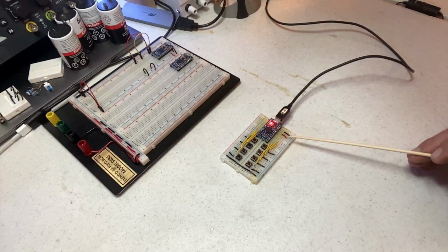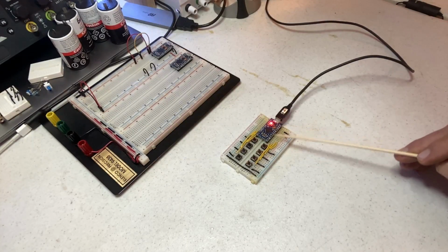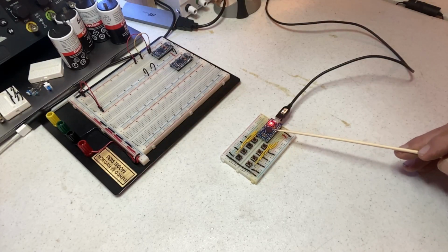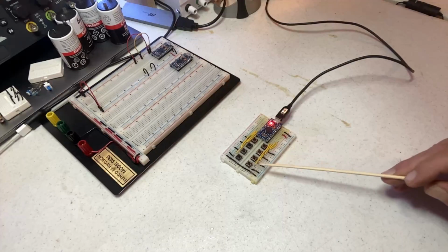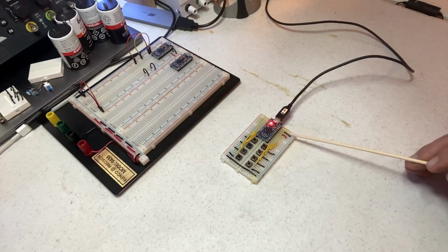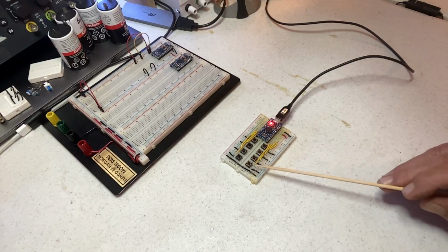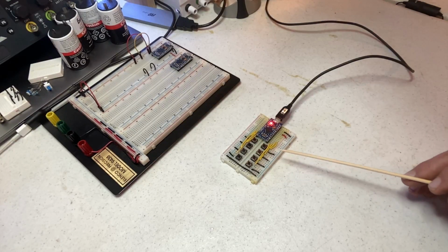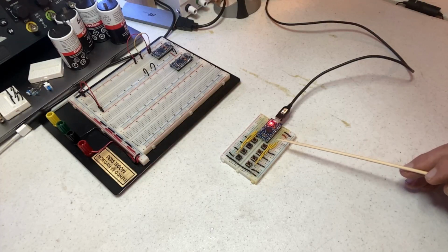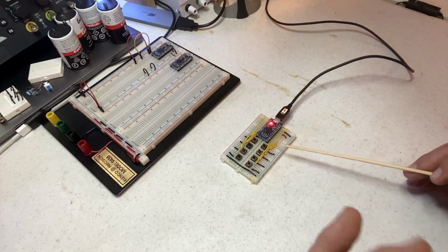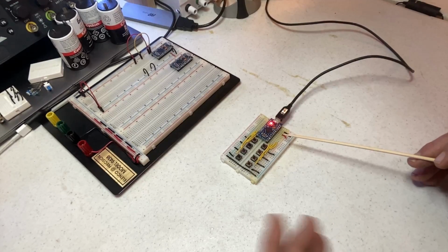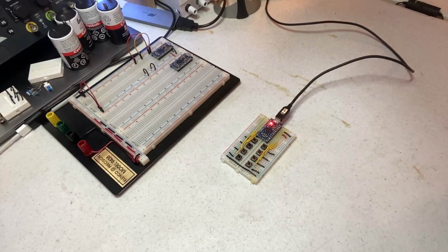Technically I don't need this red power jumper because I'm not using any power. What I'm doing is using the internal pull-up resistors on the pins inside the Arduino, which you'll be able to see in the code. And then I'm just taking the ground through each button and bringing it back into a pin on the Arduino to pull low. So when I push a button, it'll pull that pin low, which I can latch onto and do something. In this case, I'm going to send a MIDI message up to the host. Real simple little device.